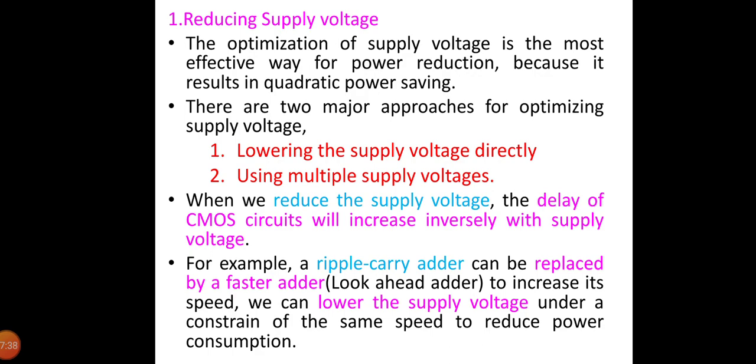So the approach presented trades off area for power, as the resulting area is approximately 3.4 times larger than the original design. This technique is only applicable when the design is not area constrained. Furthermore, parallelism introduces extra routing overhead which might cause additional dissipation, and careful optimization is needed to minimize this overhead.